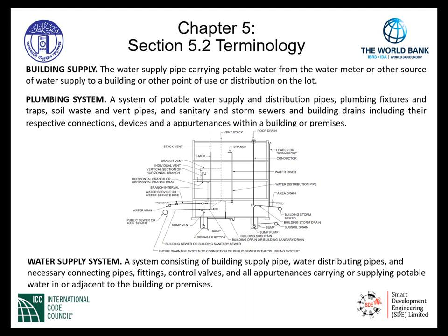As can be seen in the graphic here, by gravity, all of the sanitary drainage is located at the lowest point and discharges out of the building through the building sewer into the main public sewer. And the piping within the building is connected, of course, to fixtures that discharge waste and sanitary drainage downward. The last system that we look at is to the right on the graphic.